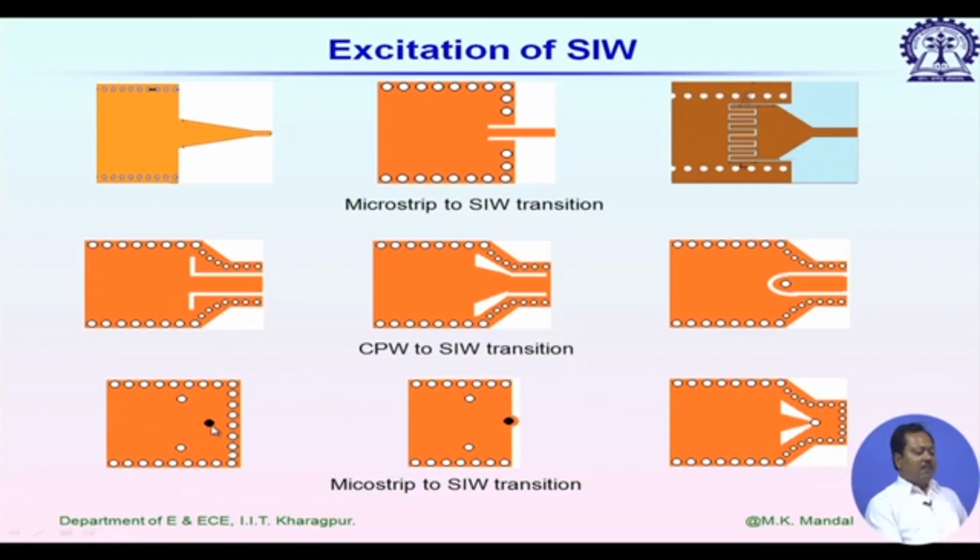And instead of a shorting wall, we can also use one open circuited wall. In this case, you can see the central conductor is directly soldered to one open circuited end. So, we do not need any extension, but again we are using similar matching vias here, and on the right hand side again a shorting wall, but with different geometry for impedance matching.